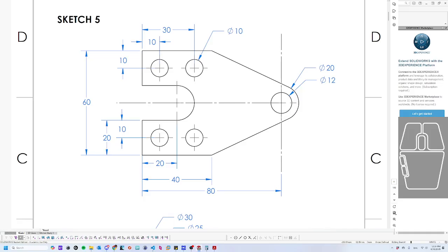The last thing we need to add are 4 circles on the legs. So I'm going to add those. Okay. Now let's add some dimensions. Again, I always like to start with one of the larger dimensions. So this needs to be 60 millimeters, because the first dimension will scale everything, and adding a larger dimension means that the outside is defined, and then you can slowly work your way towards smaller and smaller details.